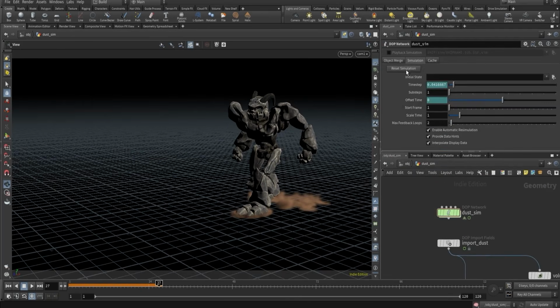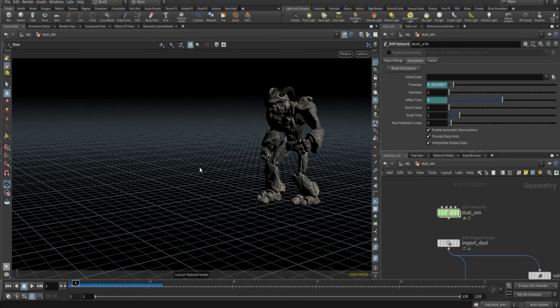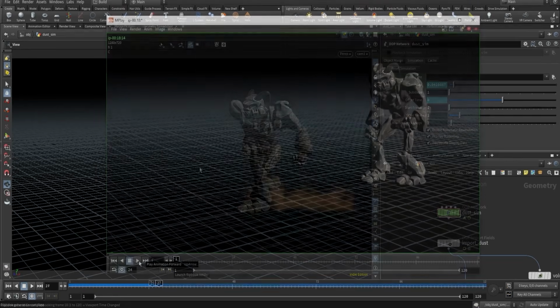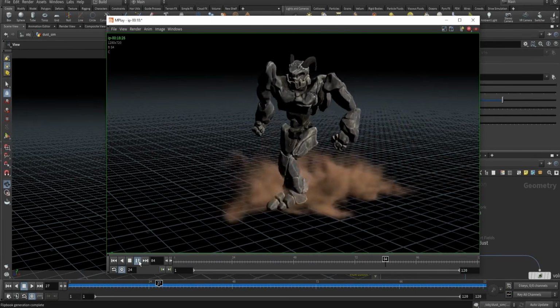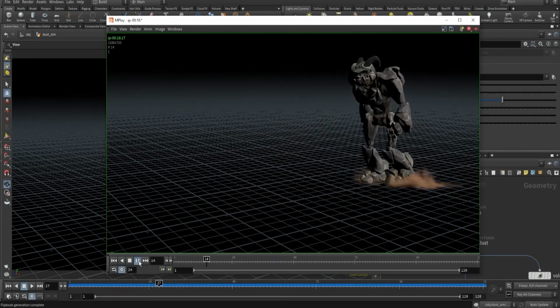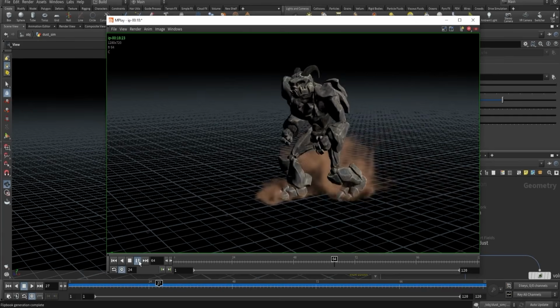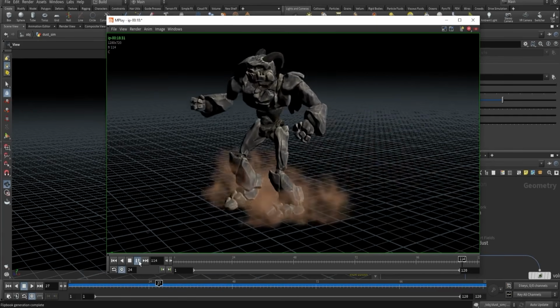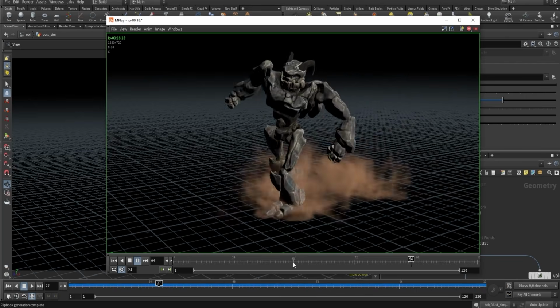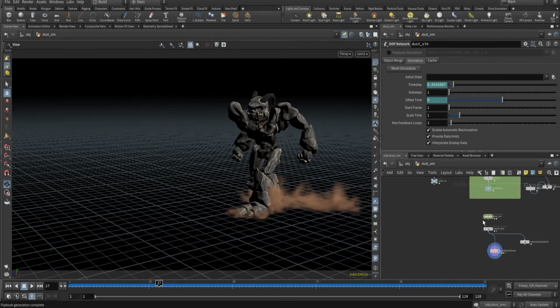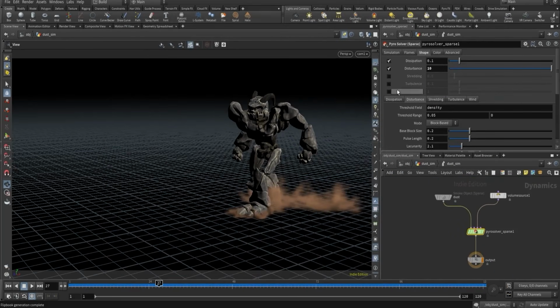Let's reset the simulation and check the difference. Yep, we can see some difference. Make a flipbook. Yeah, this doesn't look right. So what's happening over here? The disturbance is working, but it's continuously adding noise till the end. We don't want that. As I have discussed, it's a good idea to add a microsolver after adding velocity.